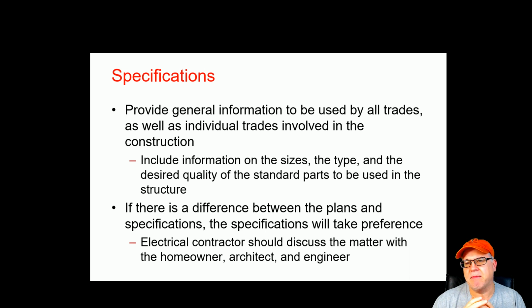And any time you'll have the drawings, which are the plans, blueprints, and then you have specifications for specific products maybe, always remember that the specification is going to take preference over the drawing. The drawing is just if you're lucky enough to get a laid out drawing that tells you exactly where to put everything, at that point, you follow that. But if there's any conflict between something on the plans and something in the specifications of a product listing, you want to go with the specifications, okay? Always takes precedent over the plans.